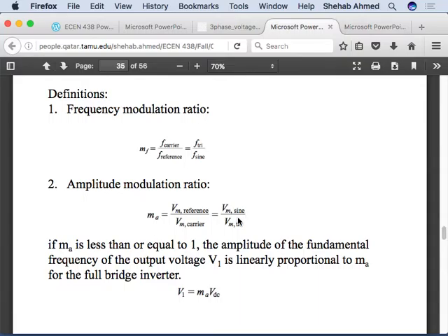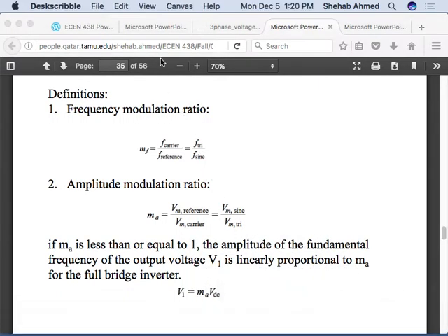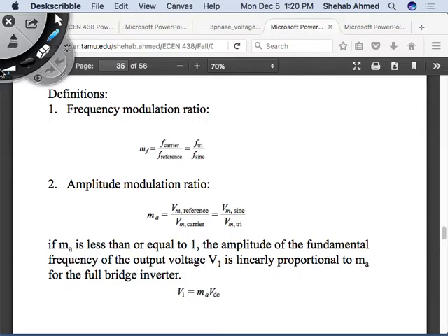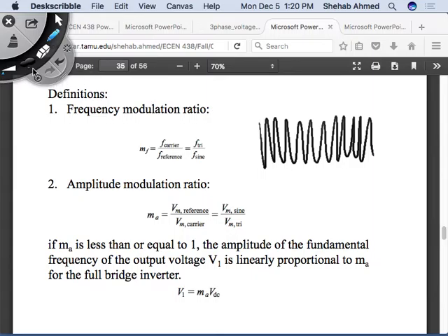You're going to change the value of your duty ratio, which is your sine wave, but your triangular waveform will always be the same, right? The carrier never changes, and you're intersecting it with your reference. Your reference will take on different values depending on whether you would like to see a large output or a small output.